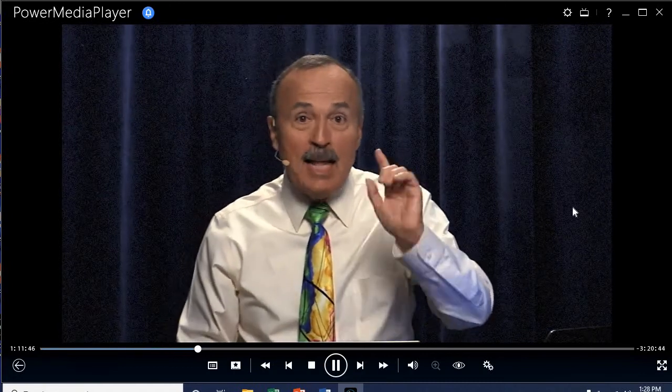You know what? We got a streamer, Ravinda from New York, who says, Mike, what about if you have a 208 volt primary supplying a 480 volt secondary? You know where you can take a transformer and reverse it? Right. Mike, we need to get a graphic. Instead of being a delta Y, you're actually going to wire it from Y delta. There's nothing wrong with that. One second, we're going to get into that, but that is an ungrounded system.